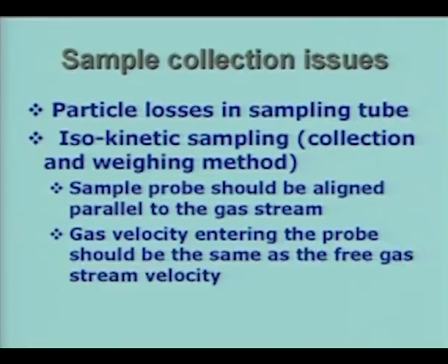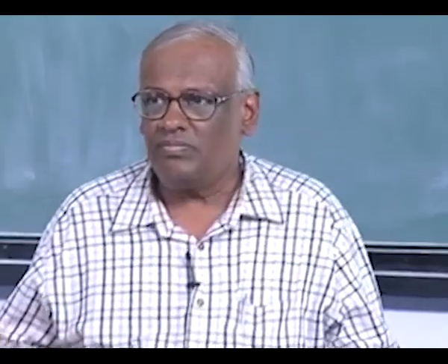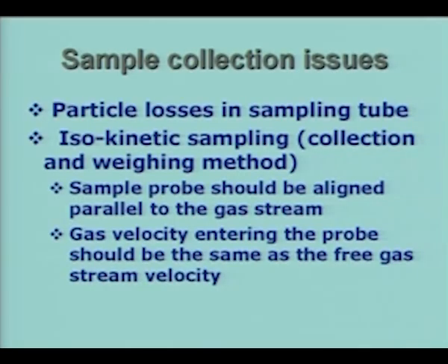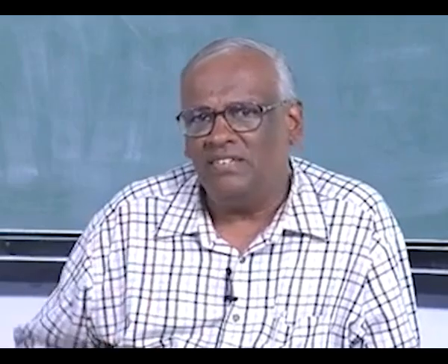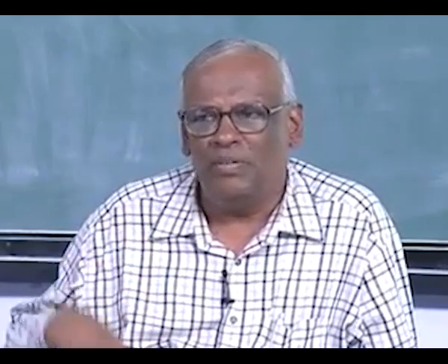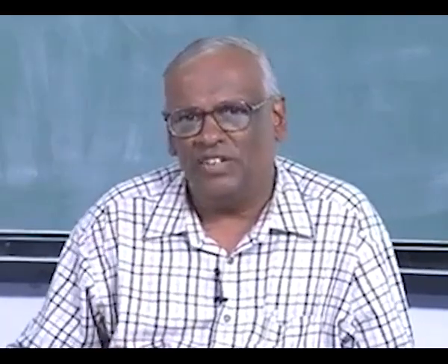For example, if you have a horizontal tube and you are sampling a gas containing some particles, the particles can settle down because the particles are heavy with respect to the gas molecules, and therefore they have a propensity to settle down in the gravitational field.